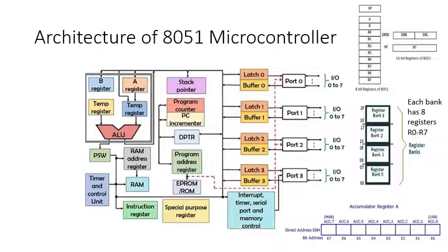All operations in a microcontroller are synchronized by the help of an oscillator clock. The oscillator clock generates the clock pulse by which all internal operations are synchronized. A resonant network connected through pins XTAL1 and XTAL2, which we have discussed in the previous video while discussing the pin diagram, forms an oscillator. For this purpose, a quartz crystal and a capacitor are employed. The crystal runs at specified maximum and minimum frequency, typically 1 MHz and 16 MHz.